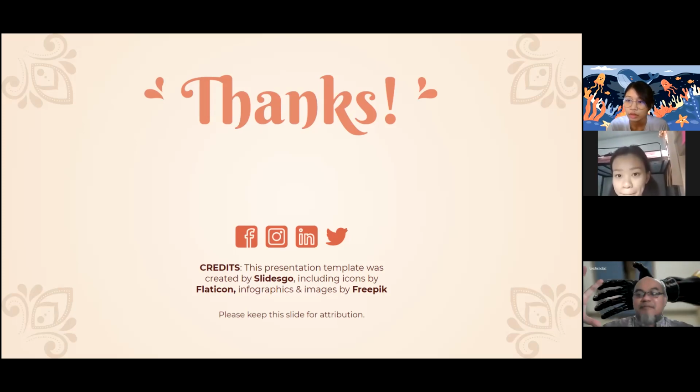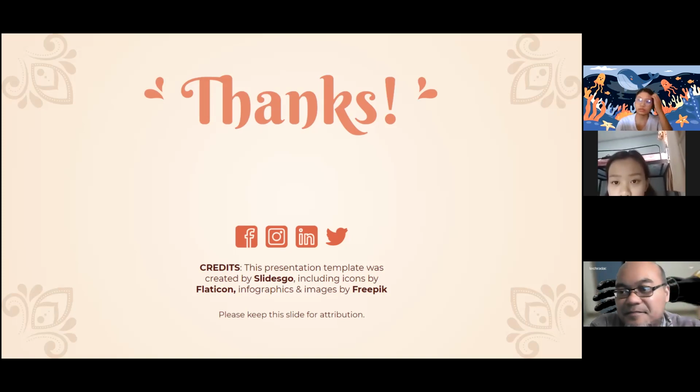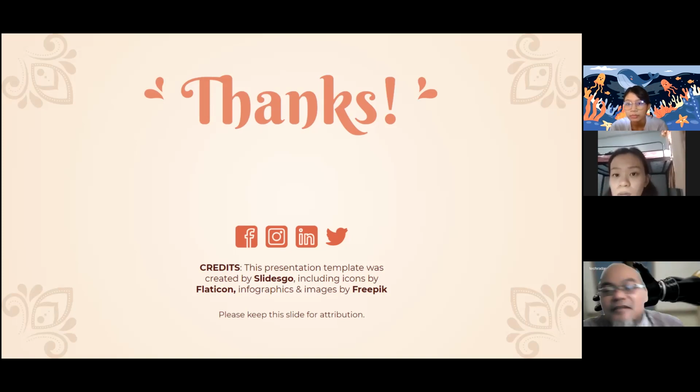In that logical step: what is the application? For that particular application, in your case, it will be dental implant. What will be the functional requirement? It should be able to withstand the chewing stress, withstand the shear during grinding, and be durable within the lifetime of the person, let's say 50 or 70 years. Based on that, what mechanical properties fit that requirement? The hardness has to be this, the strength has to be this, and so on. Then the material of choice is this. Then you confirm with the journal on that.